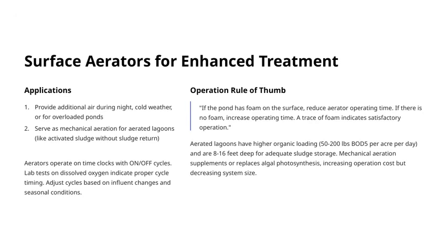Now, let's discuss surface aerators for enhanced treatment applications. These aerators are particularly useful when you need to provide additional air during times like night or cold weather, or when dealing with overloaded ponds. They also serve as mechanical aeration systems for aerated lagoons, functioning similarly to activated sludge systems, but without the need for sludge return. It's important to note that these aerators typically operate on a timer, cycling on and off.